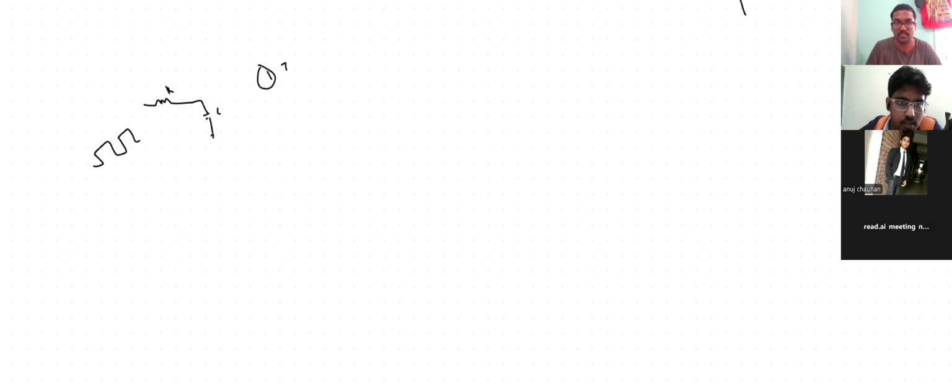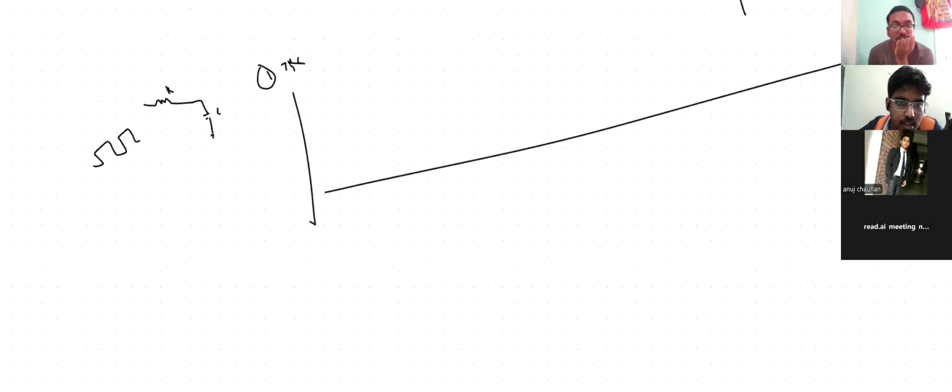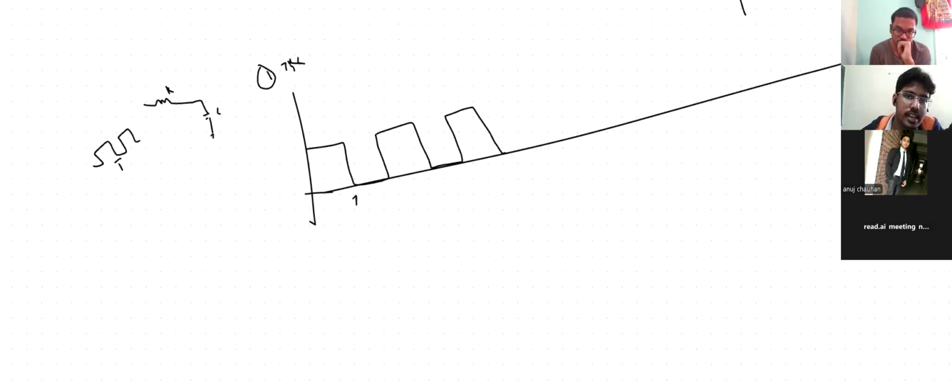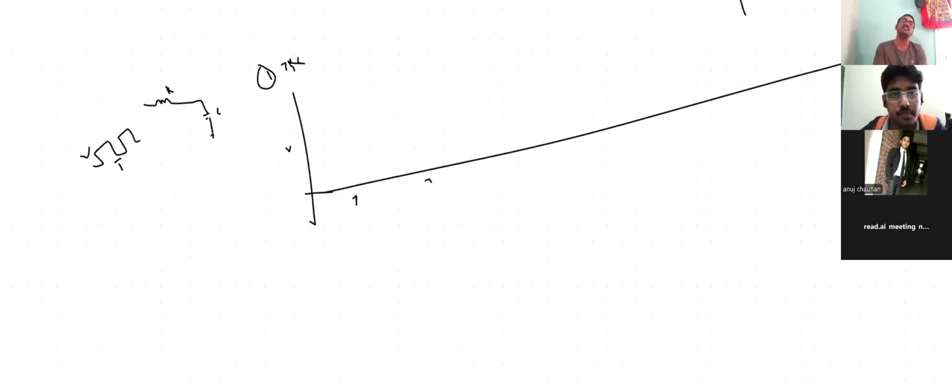First, T greater than RC, sir. Suppose this is my input now. The case when the time period is much greater than RC: our capacitor has enough time to charge, sir. Because ideally we say 5 time constants are required for an RC circuit, I mean, for the capacitor to reach steady state. So we can expect that our output will go to this. Suppose this is some V, it will go to V. And also it will discharge. It has enough time to discharge also now. This is the case for this, sir. But is that graph true for every case or only for some case?